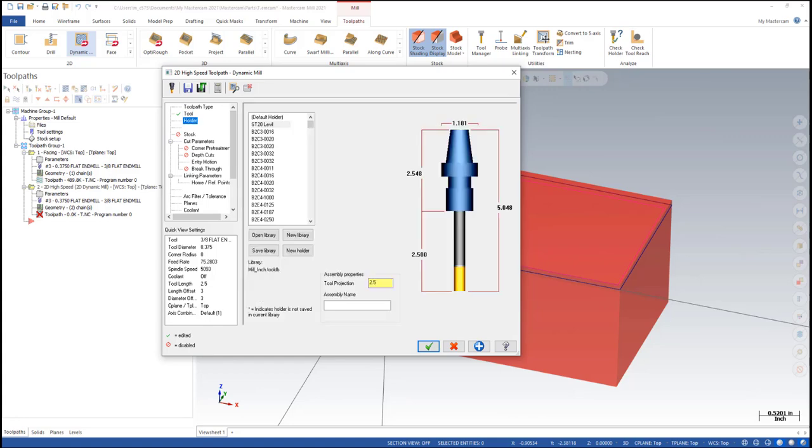Holder shouldn't really matter. Our end mill is longer than this actually. We should probably model that more accurately, but the primary thing is just to make sure we have enough stick out. So on our end mill we have 1 1/8 inches of flutes, and we're not going to clamp lower to the flutes. So I mean we're going to clamp it at like 1.3 or something. So even though the end mill doesn't show that the flutes go up to here, they do.